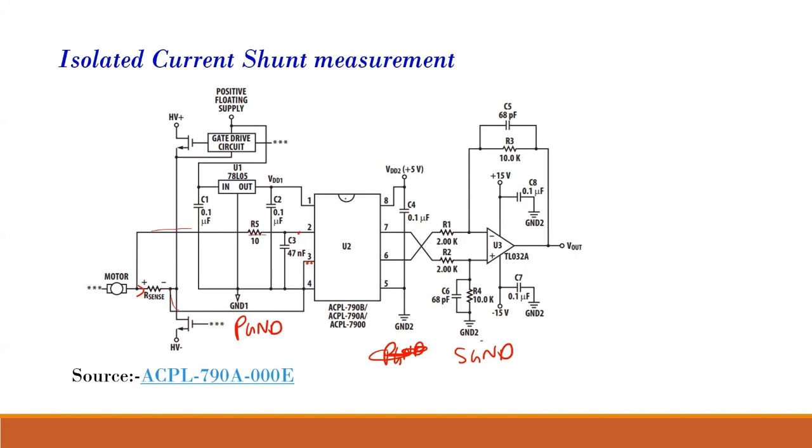That passes through my isolation op amp, which generates a differential voltage over here, proportional to the difference of the inputs with some gain. The gain of this, I think, is 8. So if V input plus minus V input minus was around, say, 150 millivolt, then V output plus minus V output minus would be 150 times 8, which is around 1.2 volt.